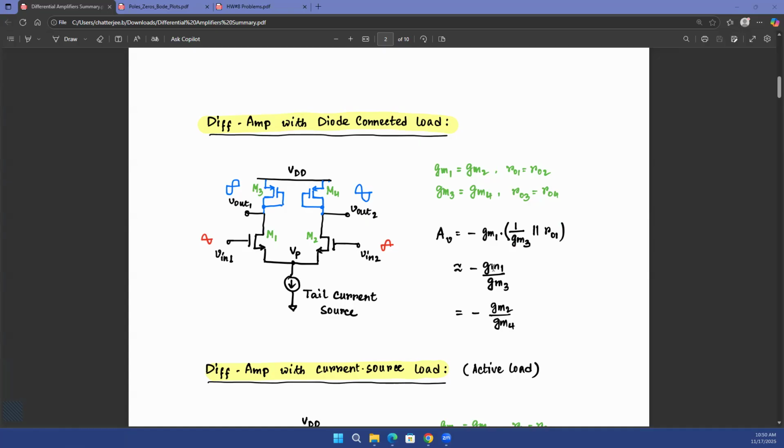That's physically going to be impossible because one transistor would be so big and the other transistor so small that we'll have trouble connecting the two together. Think of it as one transistor on your breadboard being 1,000 times larger than the other. How does that look? And how much more difficult it becomes to connect the proper nodes together. And of course, there would be the effect of parasitics and so on.